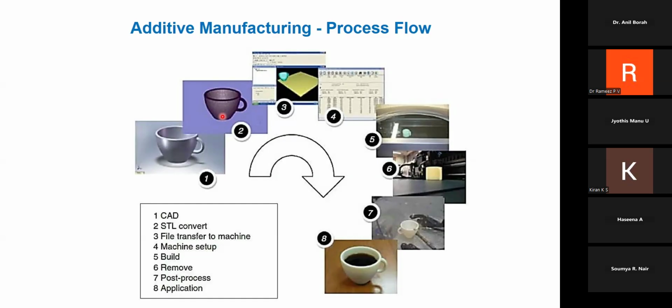Say for example you give 0.5 mm, and you want to make a 10 mm height component. Then for 1 mm you need 2 layers, for 10 mm you need 20 layers, right? So it will slice into 20 layers.